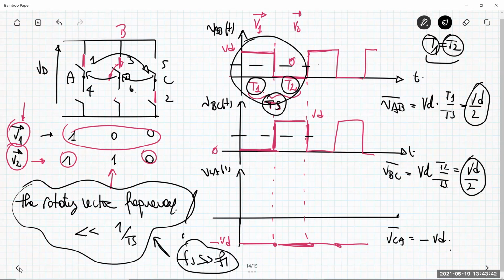In order to demodulate an average value from waveforms like this one, this is only possible by respecting the Nyquist theorem, and that gives this condition to be supported. So this is exactly the same condition that I have for any other application that is not space vectors. Here it is graphically represented, because I'm using a vectorial summation representation to synthesize something that is moving.